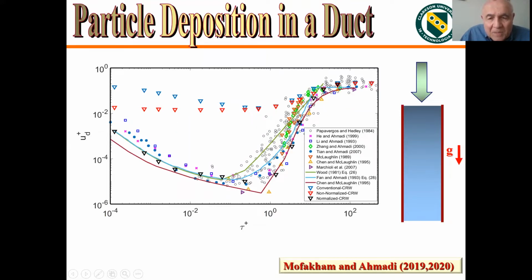And the experimental data for aerosol transport is these small little circles here, which have a U-shaped variation in this graph. And the various simulations are shown here. The ones on the top here are the conventional CRW and DRW models used without near-wall correction, which seems to overestimate the deposition in a certain size range by an order of more than 1,000 to 10,000 times. But for larger particles, it seems to be probably okay on the whole. These are various empirical fits to the data and so on.